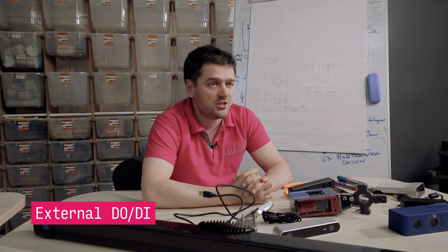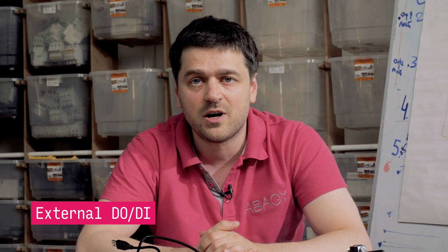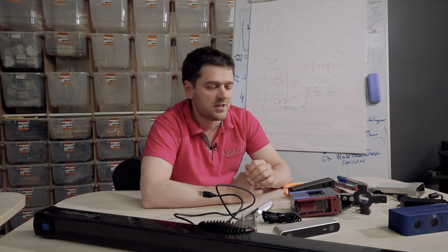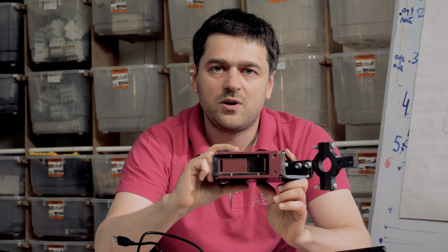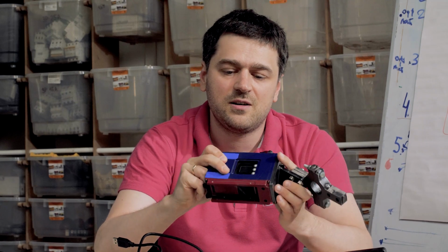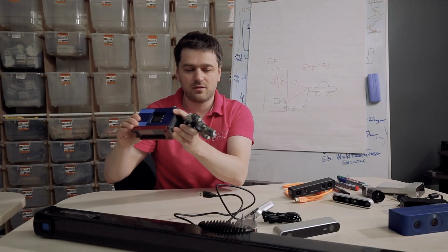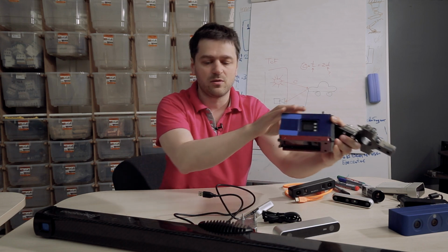Sometimes another important thing is to have digital outputs and digital inputs interfaces, because you need to synchronize cameras between each other or synchronize camera with the robot. The most frequent example here is the line scanner, where you have to synchronize the profiles with the pose of the robot to get the whole scan of the object while you are moving the scanner along the object.